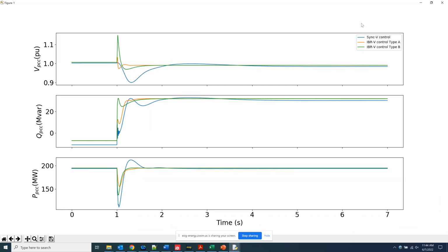So what you said is extremely true and fully correct, that some of these resources may not be able to establish their own voltage under no load condition. But there are ways to do that. Even if you have a phase lock loop, there are ways to generate your own voltage under no load condition.